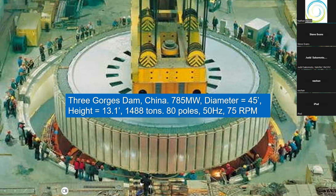So the pole face here is 13.1 feet. It's all in metric, so I converted it over. So pardon for the strange numbers, but it's 1,488 tons, 80 poles. So if it turned 50 hertz, that'd be 75 RPM. This is a huge amount of inertia spinning, fed by water through a hydro plant.